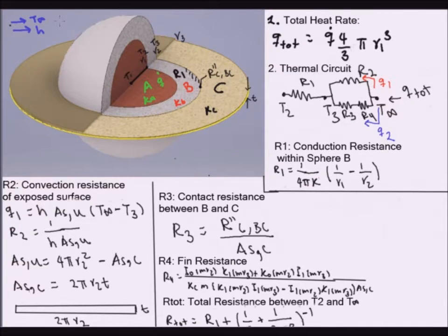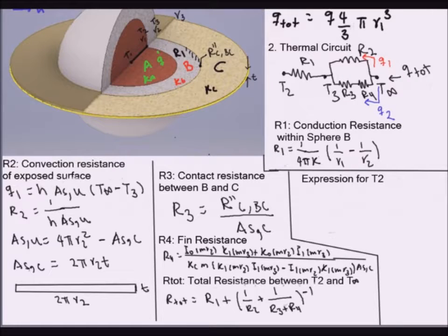the surrounding fluid. Okay, so imagine if you had more than one fin, if you had multiple fins also with the contact resistance. In this case, you would actually change the number of fins here at the numerator in this equation. Say if you had 3 fins, it would actually be here 3 instead of 1, or if you had 4, it would be 4 instead of 1, because basically every new fin that you're adding is in parallel. So I think you will go over a problem like that in class, but just keep that in mind.